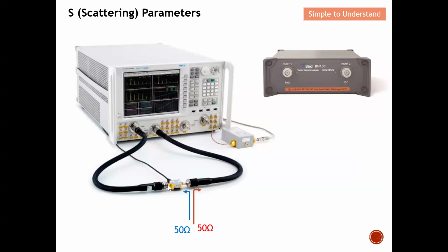And because of this, as I mentioned, when I design the filter, I put in my input and output match so as to ensure that when I look in over here it is also 50 ohm. So when this is done, maximum power transfer happens during the passband through the filter, and therefore this is the reason why we need to terminate 50 ohm on any port that is unused.